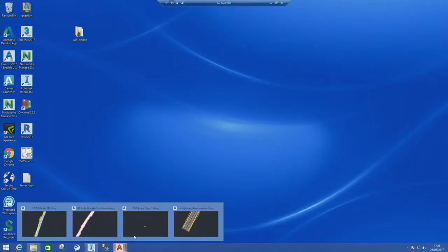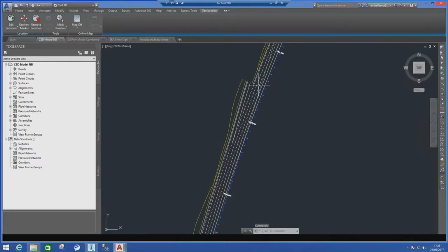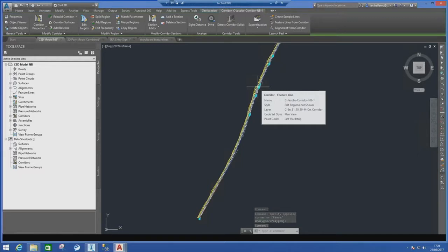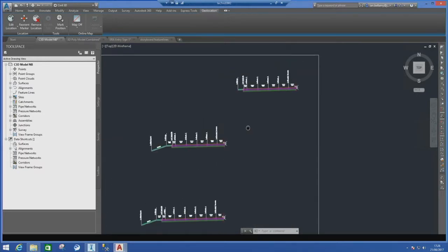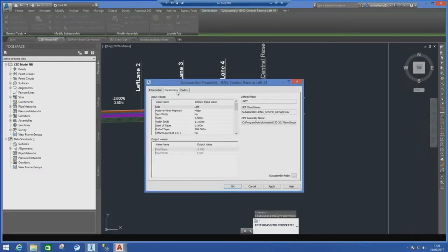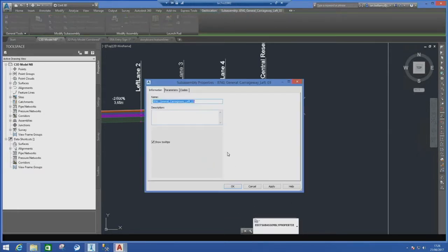so we've got a traditional 3D model, several 3D. So generally on the smart motorways, we design the northbound and the southbound, or the eastbound and westbound, on separate models just to keep the file size down. And we have, within Jacobs, made our own set of sub-assemblies that we use on every scheme. So you can see here, if I go into the sub-assembly properties, you have a code at the bottom, which is central reservation. So these codes are very important. These need to be named a specific way, and I'll show you where that's labelled, and so we know what to name them.